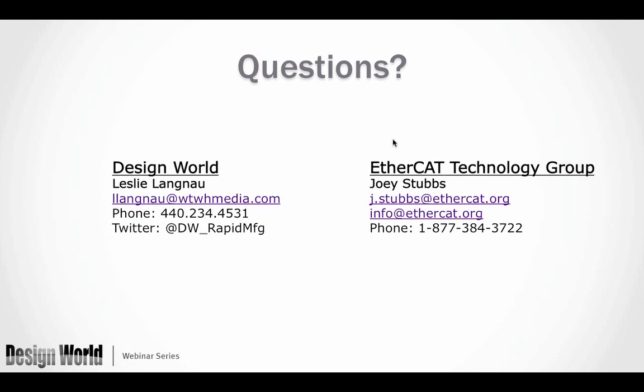And the distributed clocks take advantage of the way EtherCAT uses the frames instead of having individually routed frames within the network. So internally, the user really shouldn't concern themselves whether the synchronization is with IEEE 1588 or with distributed clocks, but in the EtherCAT world, it's going to be DCs. The performance is higher, but also because it's integrated into the slave chip, you get the direct inputs and outputs to the wire directly from the chip and directly from the commanded time or latch time. So you don't have another layer of drivers to go through from a 1588 support chip to whatever device you're controlling. So as an overall system, it's much tighter.